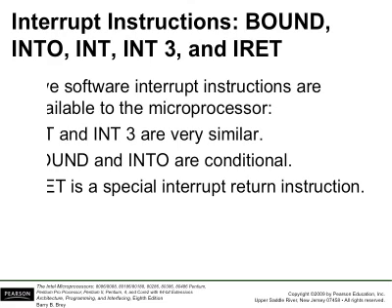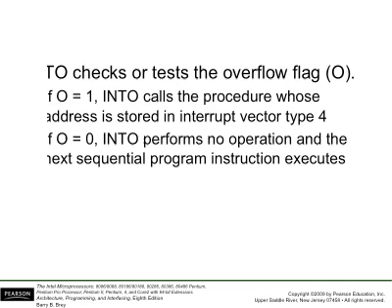Also, we have IRET, which is a special instruction used to return from these interrupt service routines. The BOUND instruction takes two operands and compares a register with two words of memory data. INTO checks the overflow flag.